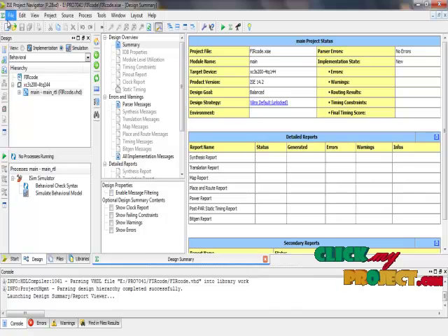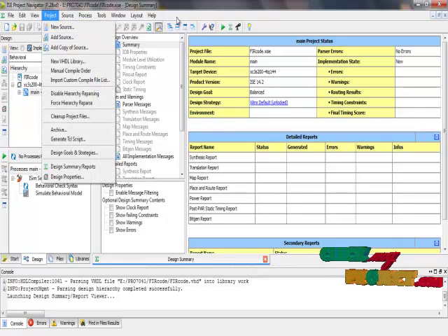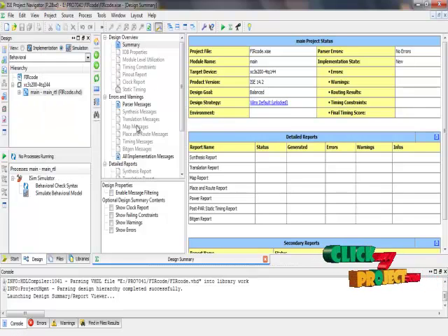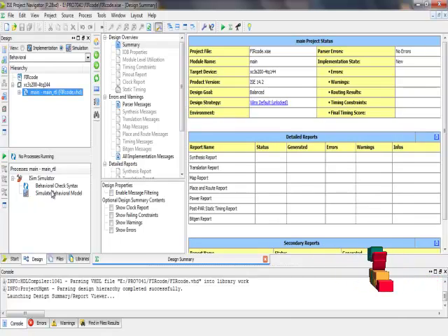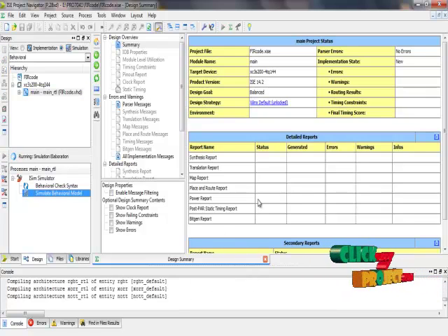For the new project, click on file and then create, and give the option create new project. Specify the folder to which we have to save our project. Then for the source file, click on the project and give the new source. The program space will be opened. Then add the new source file to our project. For the simulation result, click on simulation and then main, and double click on simulate behavioral model. The output will be shown in the iSim.